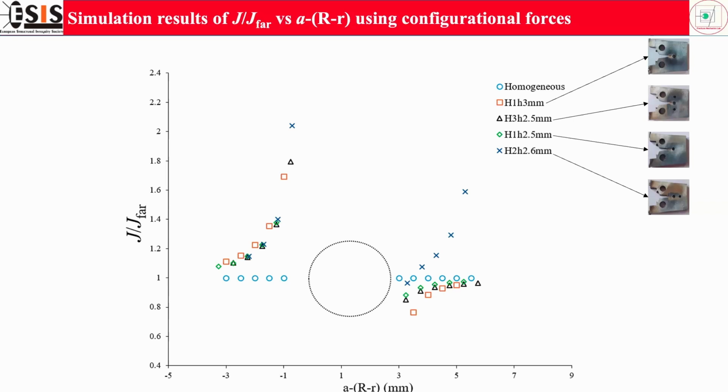So here, in this case, we can see that this rectangular bar, the hole of the diameter 3 mm has a higher crack driving force in comparison to the other one, which simply indicates that if we increase the hole diameter for the elastic plastic material, the crack driving force should be higher as compared to the other one.